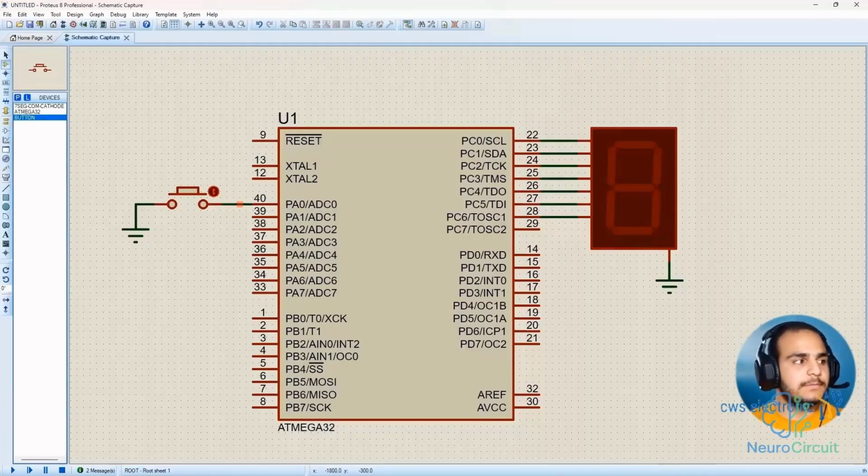Which is what? That is a pin that is set as an input because it doesn't have any voltage applied to it and is left floating. In the real world, it picks up noise. Meaning, if that pin isn't connected to anything, it will randomly switch between 0 and 1, and it doesn't matter whether you've pressed the button or not, because it's not connected to anything. It's constantly switching between 0 and 1 due to environmental noise.